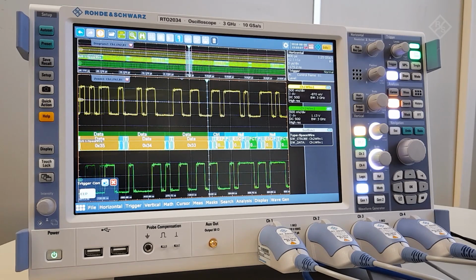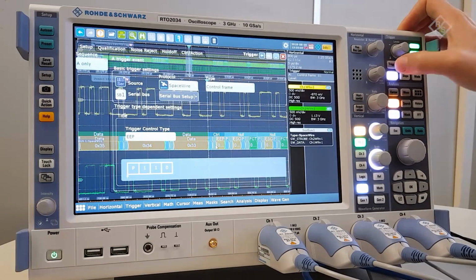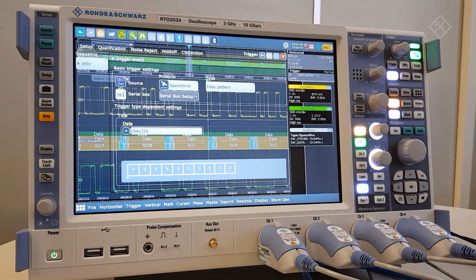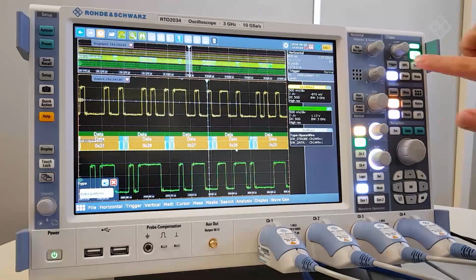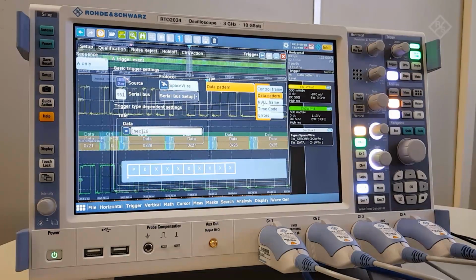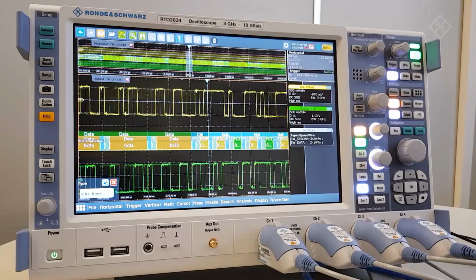The first one we saw, the FCT, is a token for flow control. The scope also had the option of any, but we saw three. Now we can trigger on a specific data value, for example, 26 hex. So we have 28, 27, and then we're triggering here on 26. And we could select other values as we want. But let's go to a different type, which could be useful for initialization: triggering on the null character.